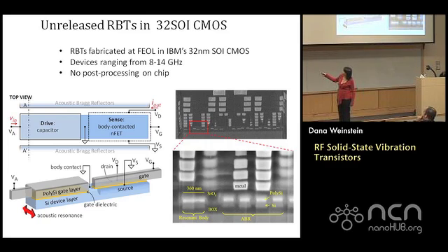You can see in this SEM, here's the resonant cavity if we cut here. Using silicon and polysilicon layers, oxide surrounding it, and then acoustic Bragg reflectors using the same material stack on either side. There's an identical side on this.